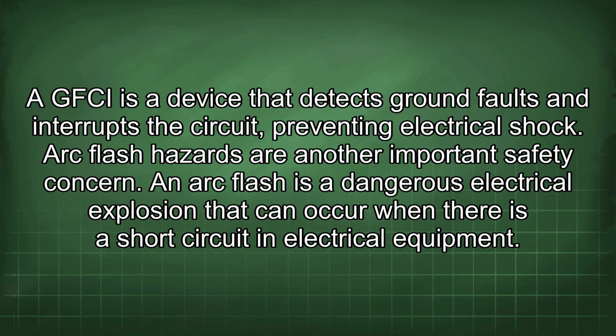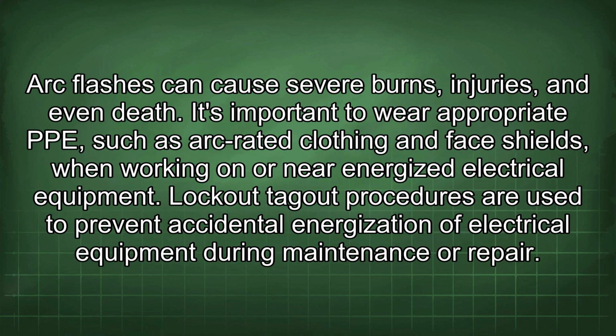Arc flash hazards are another important safety concern. An arc flash is a dangerous electrical explosion that can occur when there is a short circuit in electrical equipment. Arc flashes can cause severe burns, injuries, and even death. It's important to wear appropriate PPE, such as arc-rated clothing and face shields, when working on or near energized electrical equipment. Lockout-tagout procedures are used to prevent accidental energization of electrical equipment during maintenance or repair.